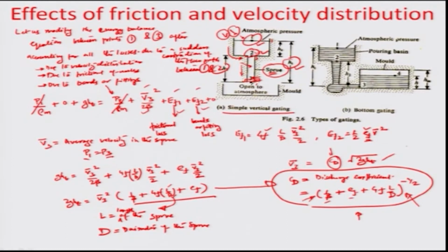Then, starting from there and trying to see what the flow regime is, whether it is laminar or turbulent, we can estimate iteratively what the C_D value is, so that the actual value of V3 could be slowly converged at. With 2 or 3 iterations, you are able to come to a point where you have a perfect convergence of the V3 term while doing calculations for such molds.